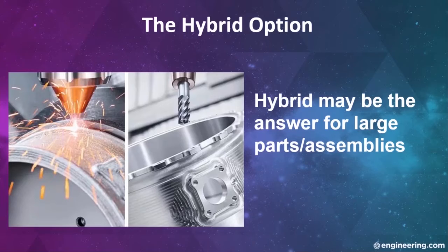Hybrid manufacturing, combining metal additive and machining, can be used to avoid the drawbacks of both methods. It could deliver larger, more complex shapes with surface finishes, flatness, and concentricity that allow assembly as machined without those post-processing steps needed with additive-only technologies. This particular machine is from DMG Mori, and like others, it also has MRO applications.